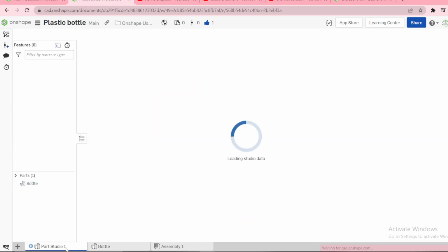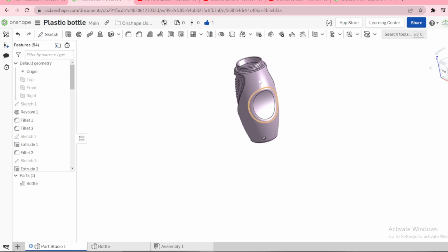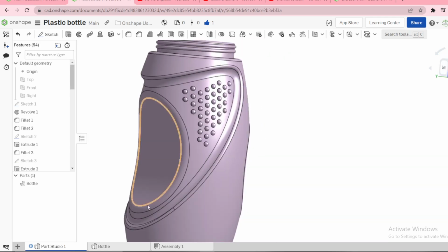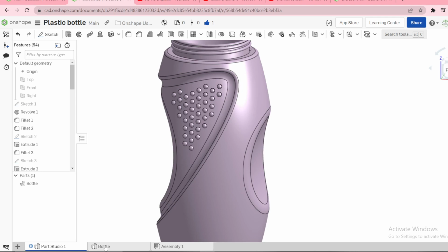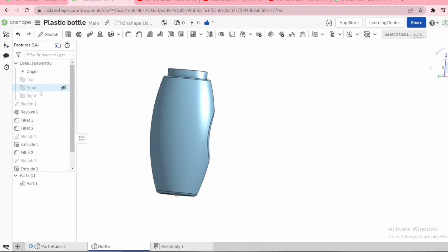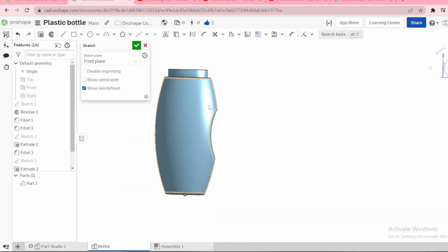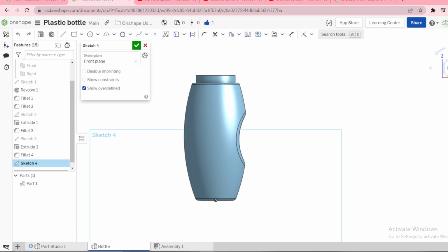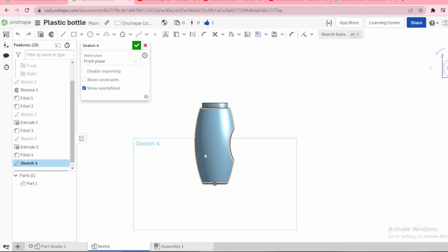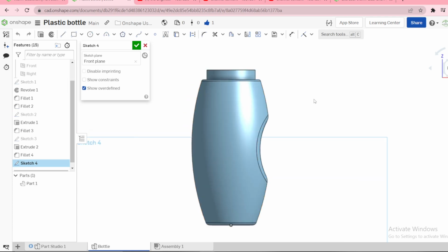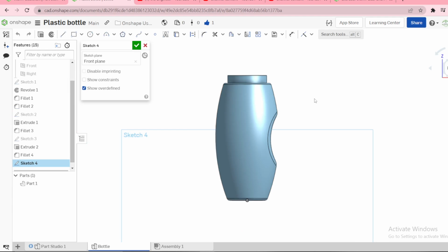Next, we need now to design this cutout, this side. Let's now go back. We go back to front plane, now sketch normal. I need several lines here. First line, I need a line that passes through the center of this. Therefore, let me activate the initial sketch. A line that I can use this. Let me use it instead. Yeah, I can hide.